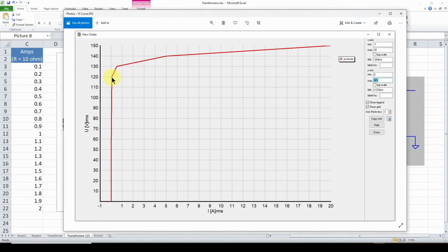However, at some voltage above 120, suddenly it's going to be very nonlinear and very, very low impedance, which means a lot of current is going to flow. So this is just a guess I made of a characteristic curve, as it's called. I'm saying that maybe at 130 volts, you're going to get up to 3/4 of an amp instead of 47 milliamps. All right. So where do I come up with this?